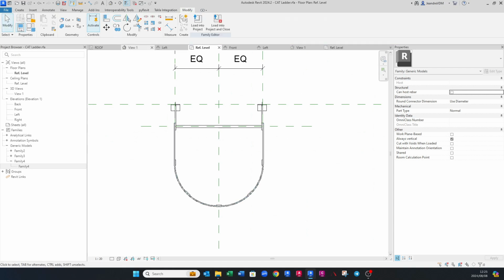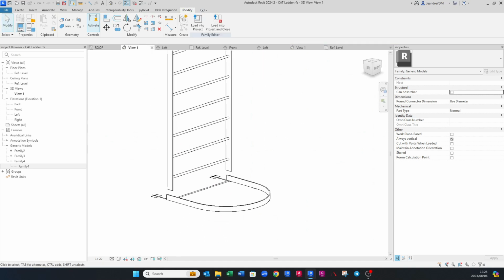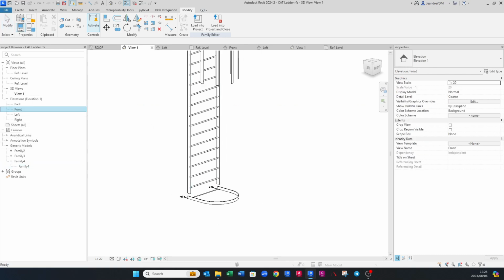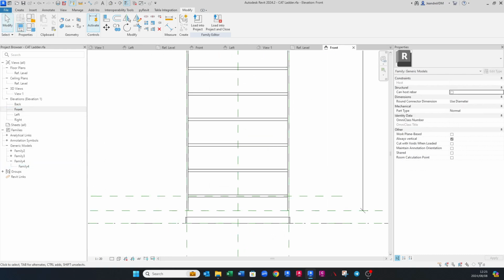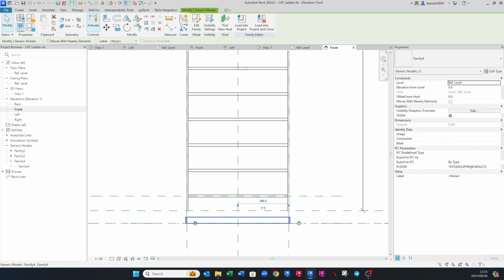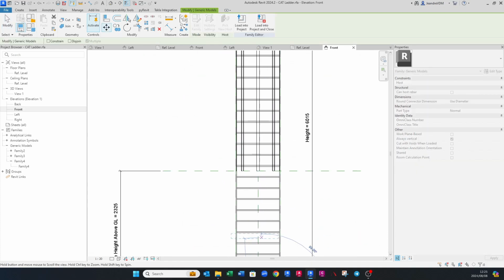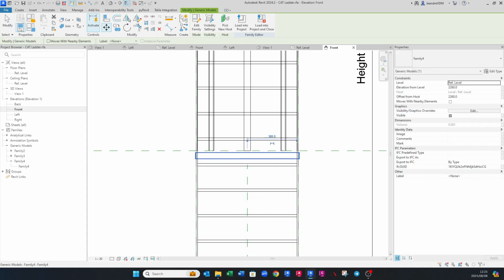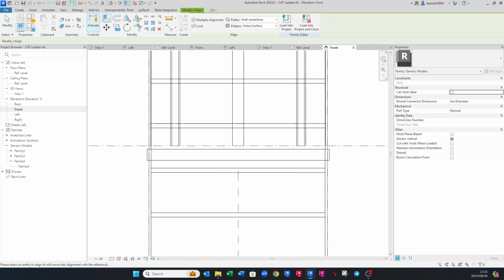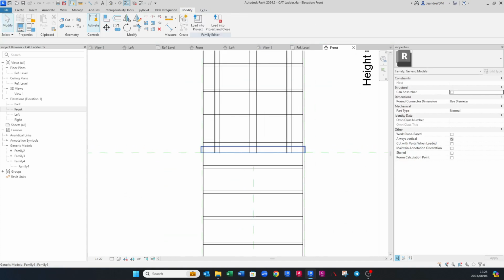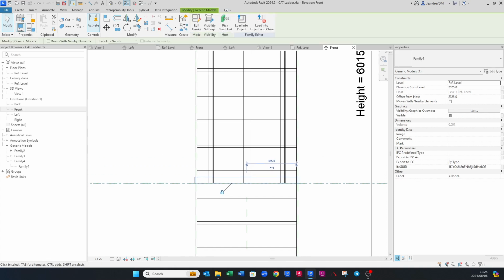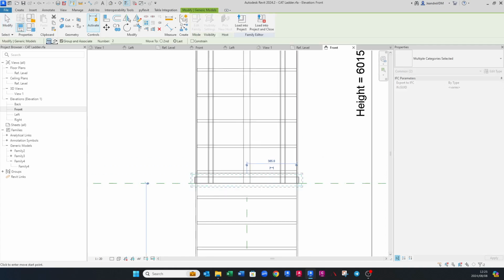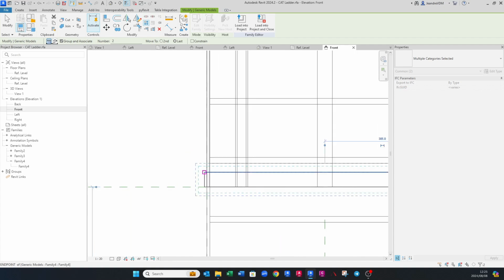Let's go to our 3D view. There it is on the ground. Okay, front view. Now we're basically going to do a similar exercise to what we did for the rods. So I'm going to just move this up. I want to align this to the bottom of this section, and then I'm going to array it, AR. Then I'm going to make sure it's on last, and then I'm going to click here.